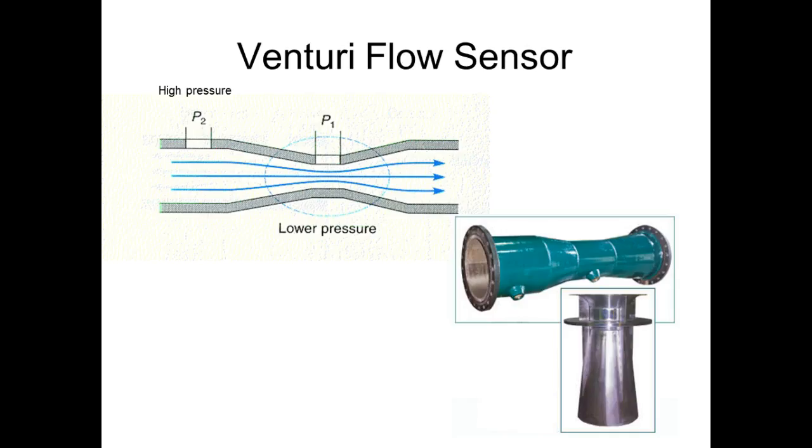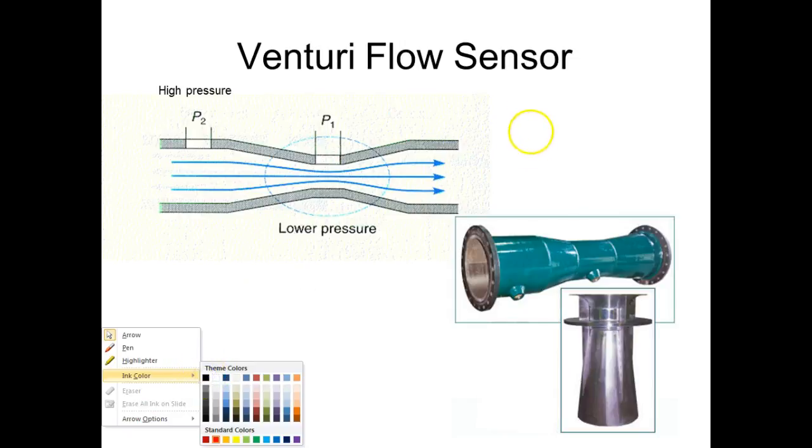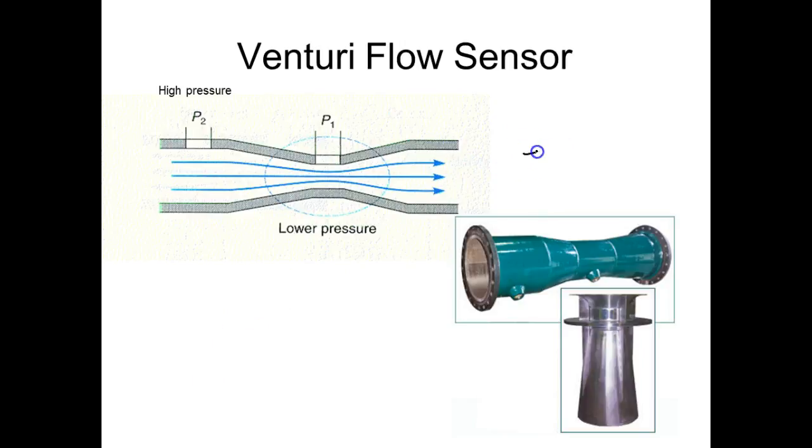So the way our ammeter works, it works on exactly the same principle. So what we do on an ammeter is we send our current through a resistor. So what we're doing deliberately is we're increasing the resistance. We call it a shunt because it has almost no resistance at all. Your high current shunt might have like 100 milliohms. And then what we do is we put our current through here. This is inside the meter, and then we measure the voltage drop across the shunt. So we measure differential, but your meter doesn't display it as V, it displays it as what? I.